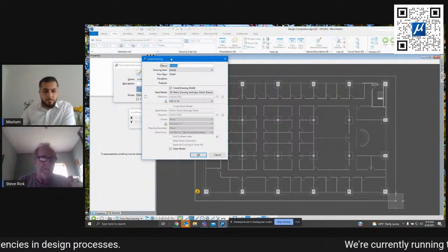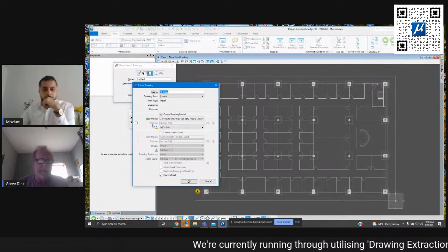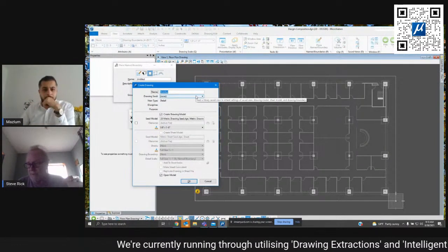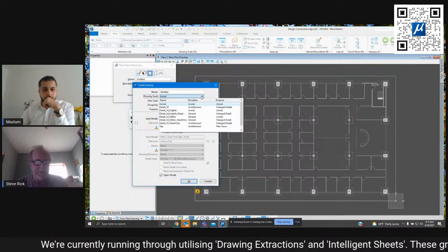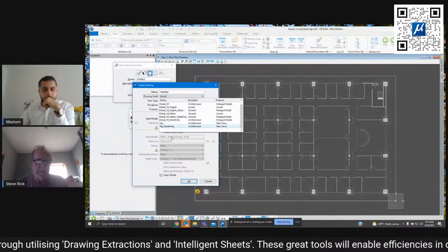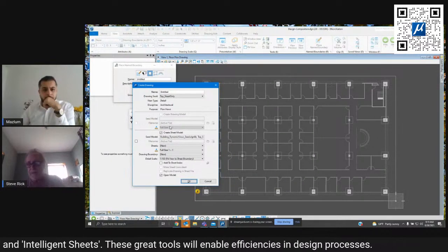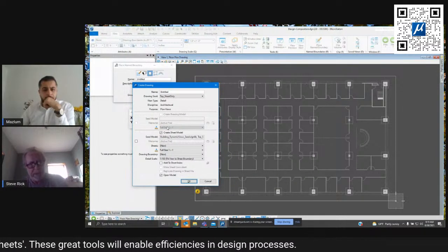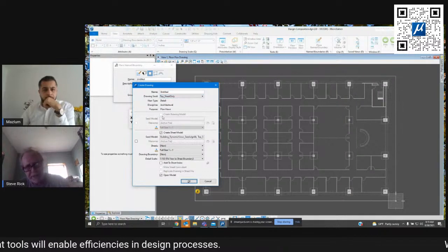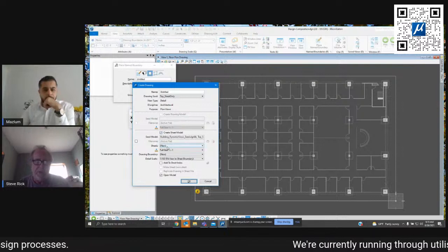And then here we go. I get the same dialog box. Okay. I have to choose a seed file just like I did before. Now this time, instead of choosing the drawing seed file, I'm going to choose top sheet only. Okay, top sheet only means that I'm only going to create a sheet. When I choose that seed file, you see it turns off the create drawing model, turns on the create sheet model, right?